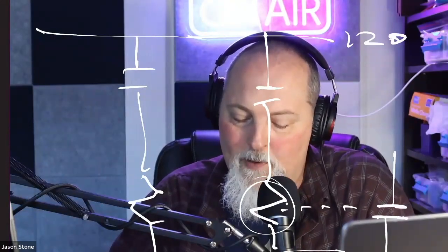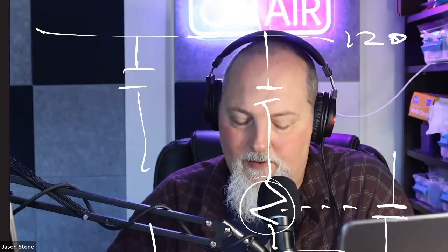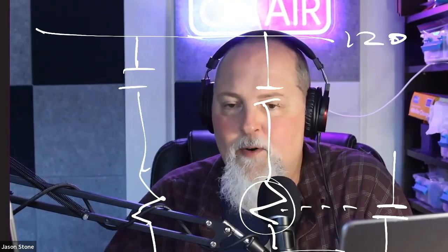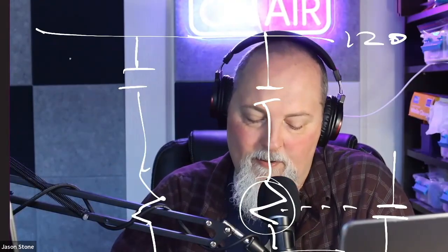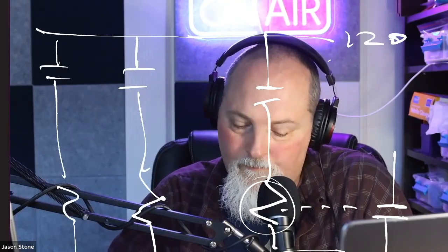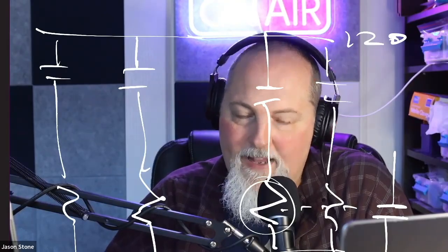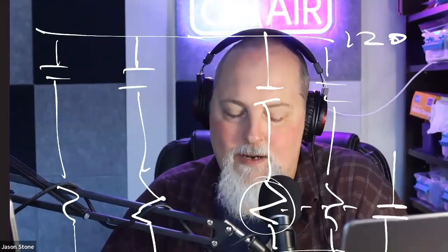And so if this relay goes bad, but this relay here doesn't, if that relay says, no, there's nothing wrong, this is fine, then we don't get a scram. We don't get the actuation. We don't get the isolation. And we have four of these things. So this is how I'll draw it, so that if any one of these components goes bad, we don't get the isolation or actuation.